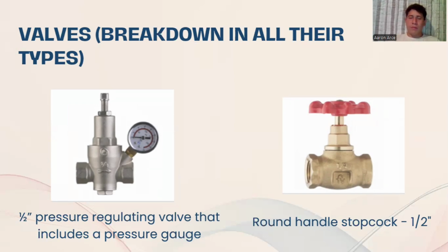Common materials include brass, stainless steel, and engineering polymers such as PVC or polypropylene. In this case, we will use stainless steel due to its resistance to corrosion, durability, and ability to withstand the typical pressures and temperatures of the system in which they will be installed.